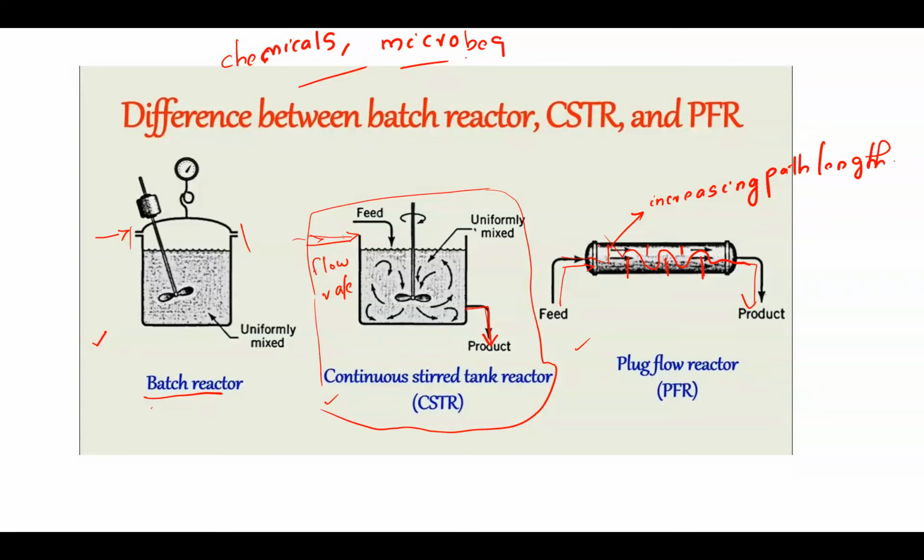So you will get more time. The handling liquid will get some time inside the chamber. Here you are not increasing the length of the chamber, but you are providing some stopping, some restrictions like this, so that its flow will be like this, and it will take some time to reach from its inlet point to outlet point, thus increasing the path length. Also it gets more time to process.